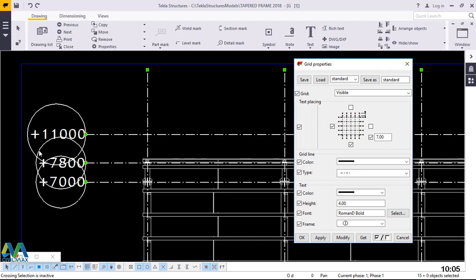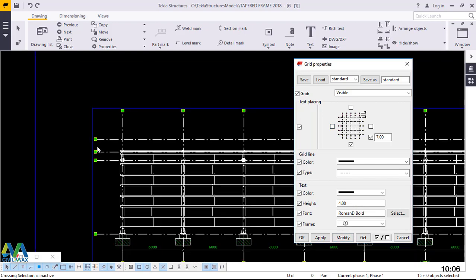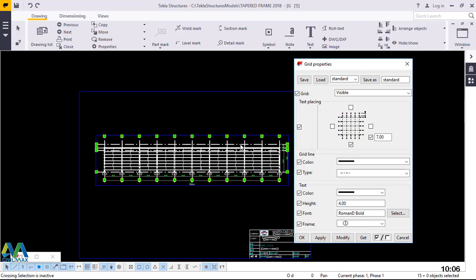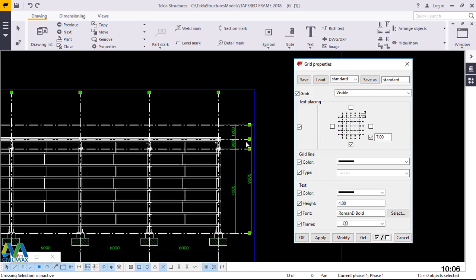Now what we'll do, we'll just do away with it. The reason why it's big is because the dimensions here are wider, so the whole area is being covered. When all the numbers are covered, you see all these circles are stretching inside each other. Now what I'll do, I'll just get rid of those grids by unchecking that, then go straight and click modify. Then we'll not have them there because we have all the dimensions at this end.